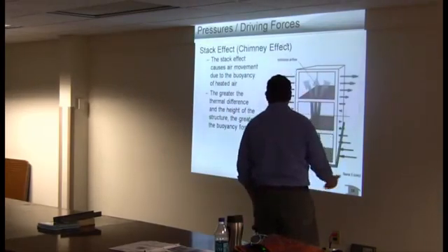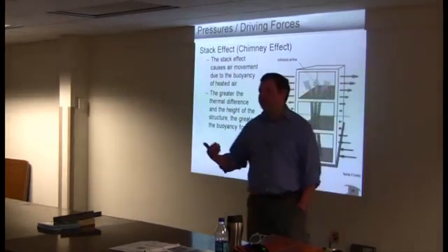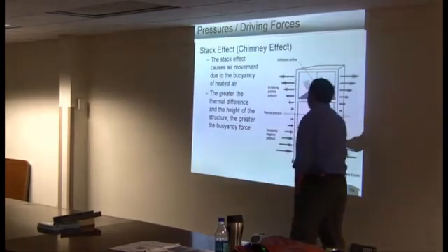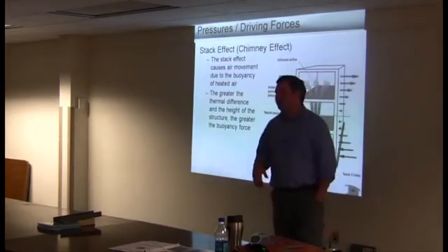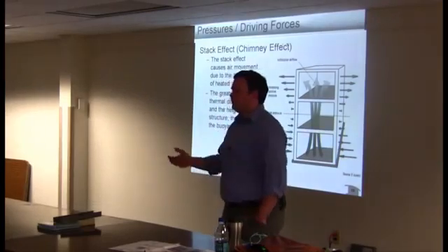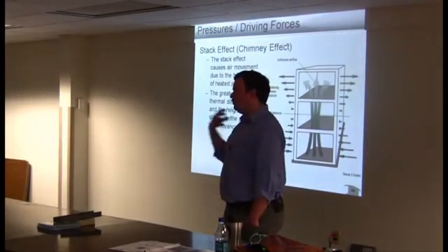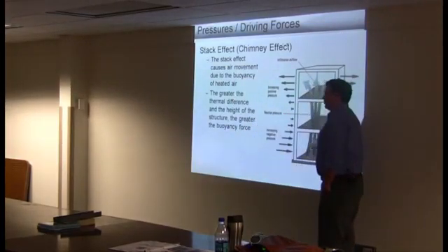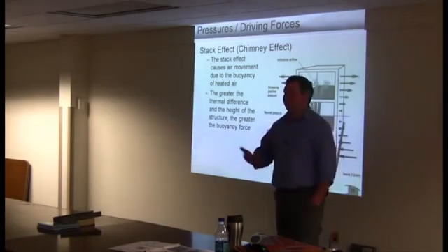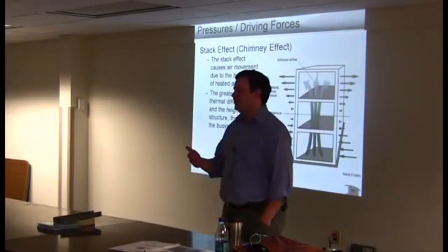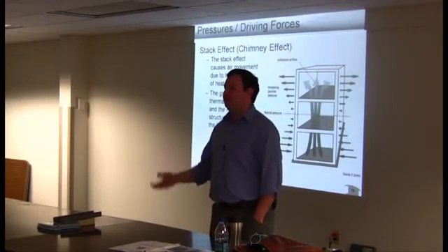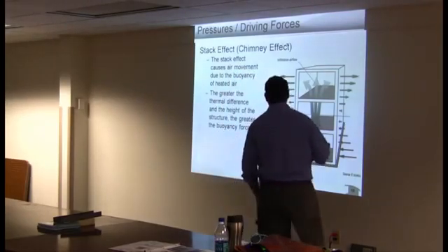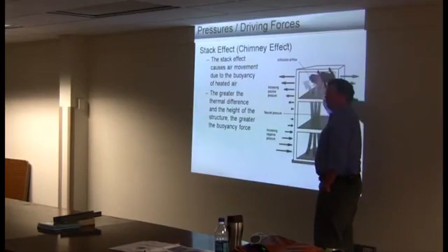So this is what I was alluding to a minute ago, stack effect. Stack effect is basically pressure differences that are driven by the buoyancy of air. The warm air wants to rise in these structures. I'll probably talk about this on Tuesday. Within a residential structure, stack effect exists, but it's probably not going to create really dramatic pressure differences. The taller a building gets and the larger the interior open spaces are, the bigger the effect you're going to have from stack effect. So when you have, let's say, a 10-story open atrium hotel, you're going to have a very large amount of stack effect in that space because you've got a big open chamber with a very dramatic height difference.